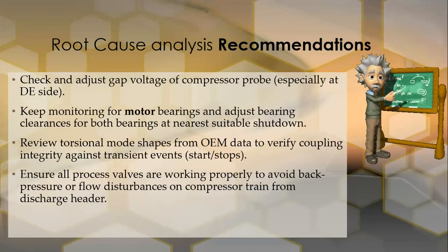Another thing that we found after writing this presentation was that we made a check on the other compressor that is identical to this compressor. As we mentioned before, there are two identical compressors like this one. And when we opened the drain lines, we also found liquid, which was shocking for the vendor, for us, and for each and every one.